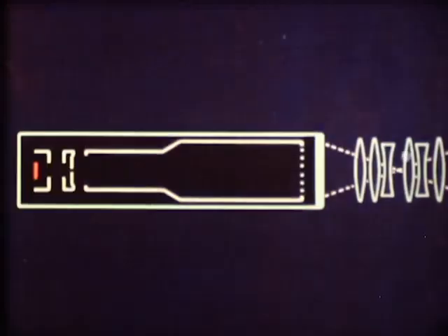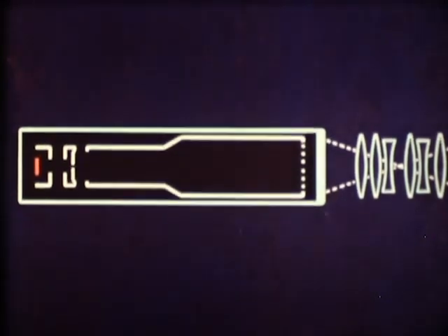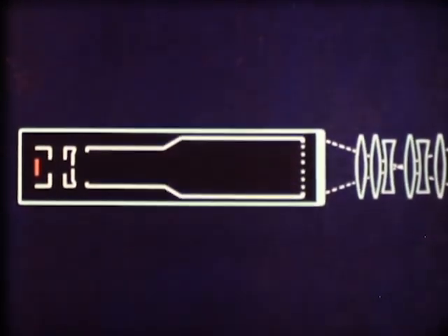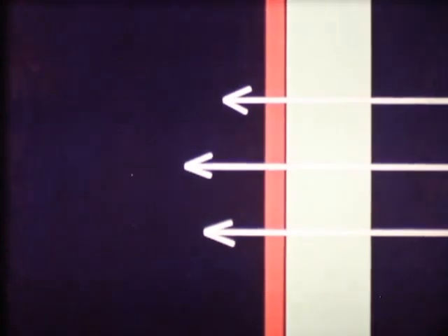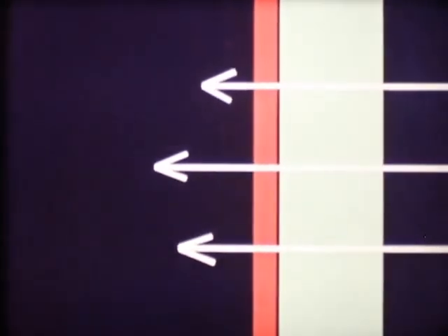But what is the effect of this scanning process on the signal plate? And how is the picture signal obtained? As we have already seen, the signal plate is situated at the front of the camera tube. First, the inside face of the glass tube is coated with a thin film of tin oxide. This layer is so thin that light will pass through it. Moreover, tin oxide is a good electrical conductor containing many free electrons.